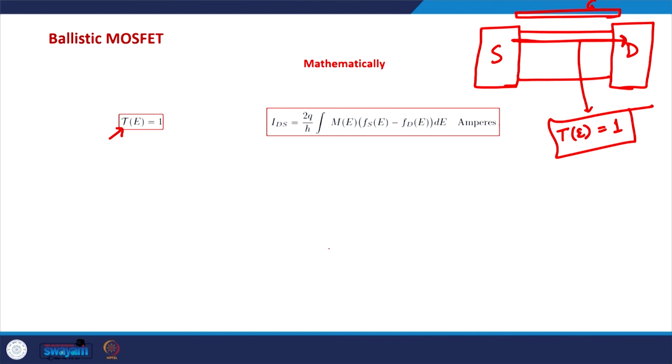This resistance is coming from the source contact, or from the interface between a bulk contact and a ballistic channel. The energy is dissipated in the contact, not in the channel.